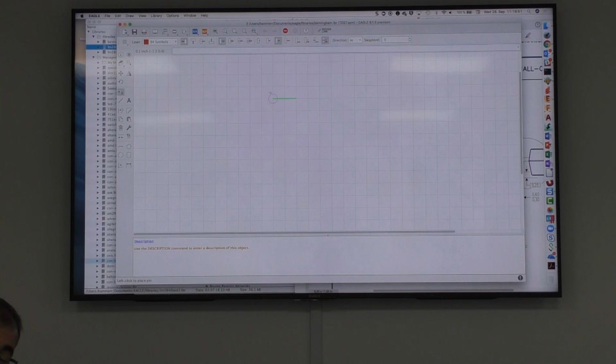And then I can decide what I can read in the schematic. I have a pin name, should it be displayed, and I have the assigned pad of the package. So I can decide should there be text for the pin name, for the pad name, for both, or no names. If you think of a resistor, then I would choose no text at the pin. It doesn't make sense to have a resistor where you have 1 and 2. That's clear, you have 1 and 2 pins, so there is no function there.